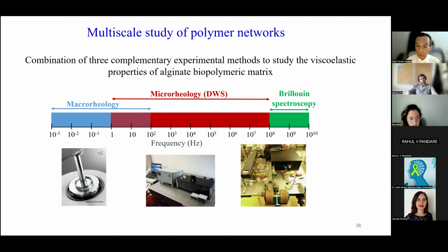So if you want to extend the frequency range of investigation of viscoelastic property, it is mandatory to combine macrorheology with other experimental investigations. Typically microrheology, diffusive wave spectroscopy, and I will show you also, if you want to extend at higher frequency, Brillouin spectroscopy.